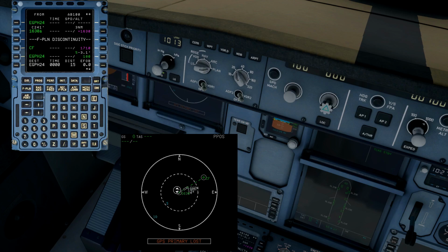So we are taking off, doing a left hand turn, and returning back to the same runway. Same runway, we'll be landing on the same runway. We are doing a 180-degree turn against the runway. We will reach the beam of the threshold, start counting 35 seconds, turn left and get back into Edinburgh runway 24. So now we need to know when we pass the beam of the threshold.